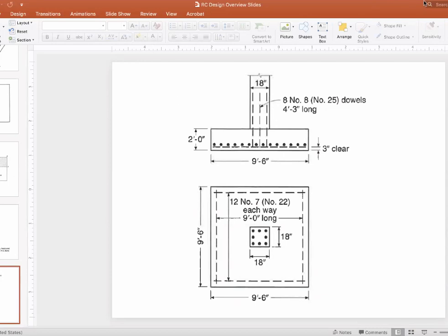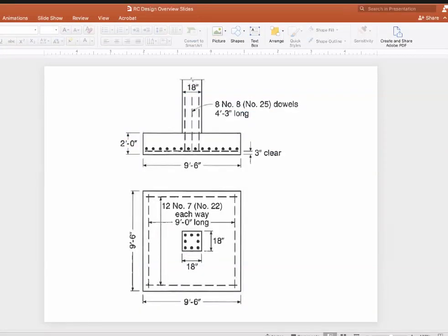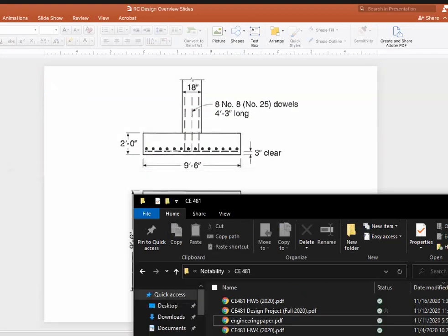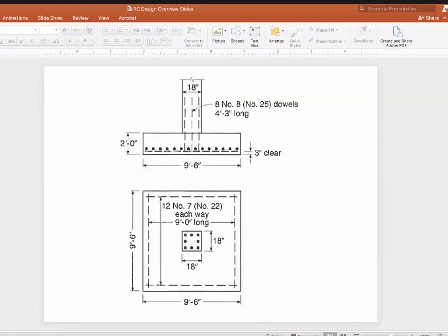Let's start there. What's the difference between the frustum consideration and the punch-out shear failure consideration? They look like they're looking at the same kind of shape. They kind of are. The frustum is dealing with just that, the end bearing actually punching into the concrete itself on a very localized basis, just having the column crush into the concrete.